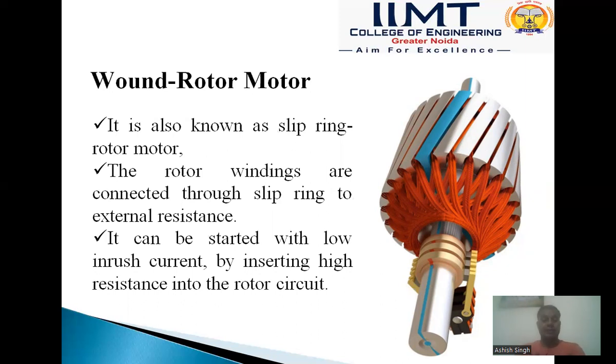The rotor windings are connected through slip rings to external resistance. It can be started with low inrush current by inserting high resistance into the rotor circuit externally.